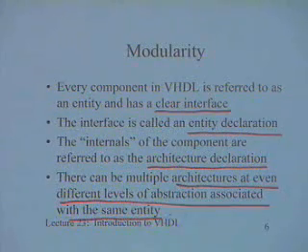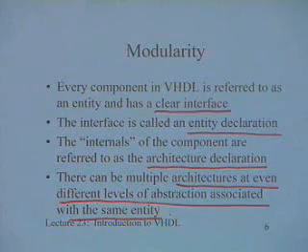and this is very, very important. So for every VHDL component that you need to have, there will be only one single entity, but it need not have one architecture. It could have many architectures, and of course, at the time you instantiate this component, you have to decide which architecture you will use.